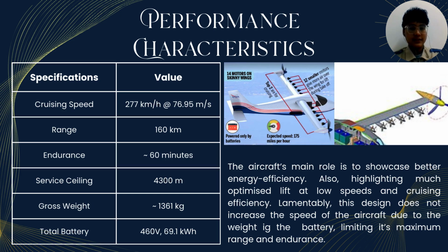Moving on to the performance of the design, the aircraft cruises at 277 kilometers per hour with a range of 160 kilometers and an endurance of about 60 minutes. It has a service ceiling of 4,300 meters with a gross weight of roughly 1,361 kilograms, powered by a 460 volt, 69.1 kilowatt hour battery pack. The main goal of this design was never about speed, but mainly about energy efficiency.